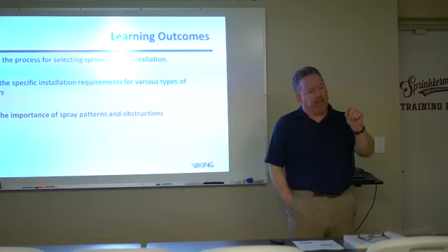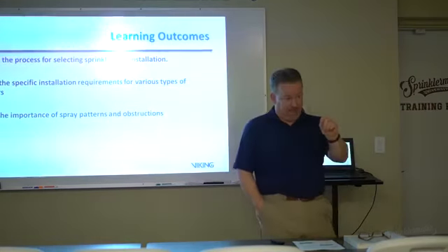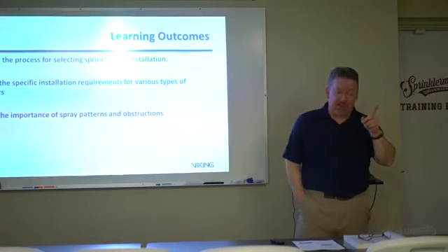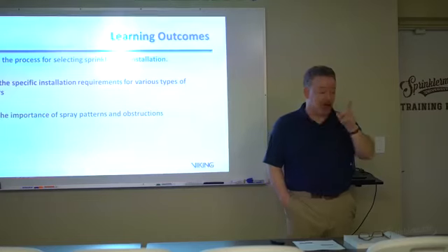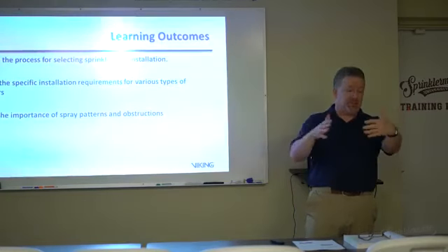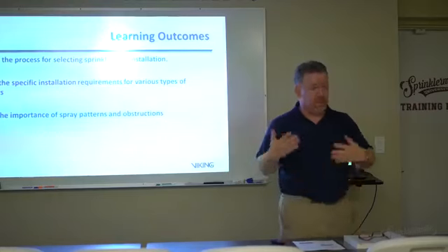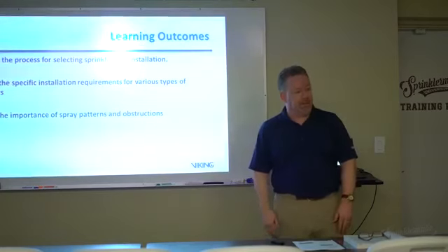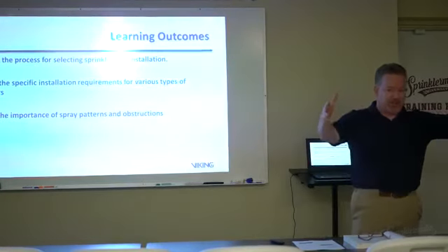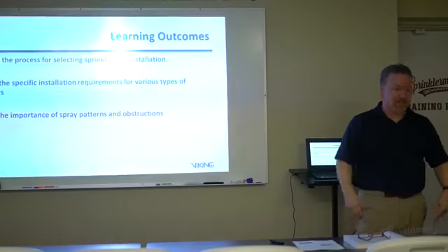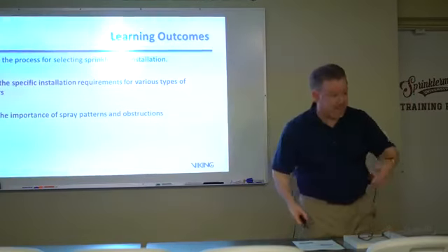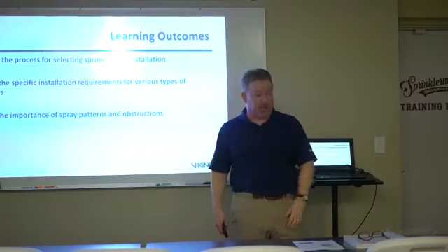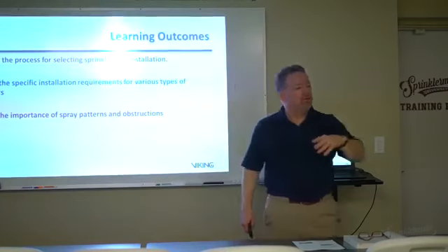You would need to evaluate a couple of things. It's not just the water supply, because it's also spacing. Right. Okay? Hazard classification, increasing the hazard classification also may impact the restrictions on the area of operation. May limit you to, say, 130 square feet if it's a standard spray sprinkler. Okay, whereas with light hazard you can go up greater than that. Okay, so we'll take a look. We'll show you how that plays in, and you'll see that it's not just about the water supply itself. It's also the appropriate spacing of the sprinklers. Both distance on the line and lines themselves.